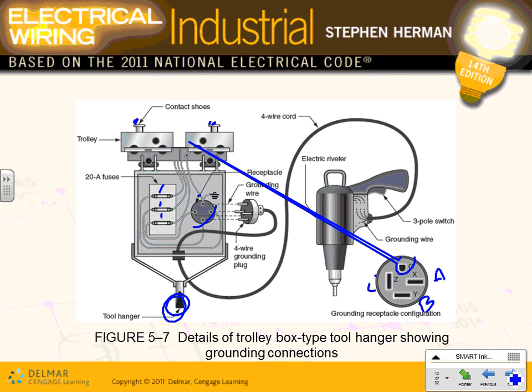Look at the plug. So you plug it in. That will act as your disconnect. Everybody understand? Because the equipment needs a disconnect. There is no disconnect here. Do you see any disconnect here? There is no disconnect. So the plug acts as your disconnect.